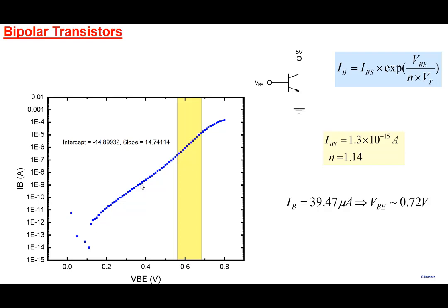What is the typical value? But what I was trying to emphasize is that if somebody says 10 microamperes and ideality factor of 1, that gives you wrong values. It gives you an all-wrong set of results; it starts predicting 1,000,000 amperes and very, very low diode voltage. So that's not a realistic number. If you have to quote numbers, you could quote numbers like these. Like in a bipolar transistor, the base emitter junction diode is given by these particular numbers here.